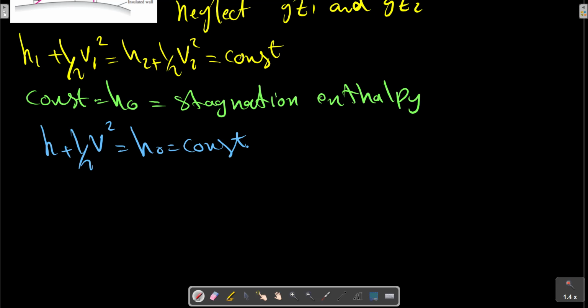The wall in this picture could be either the surface of an immersed body or the wall of a duct. We have shown the details of this picture. Typically, the thermal layer thickness is greater than the velocity layer thickness, because most gases have a dimensionless Prandtl number less than unity.